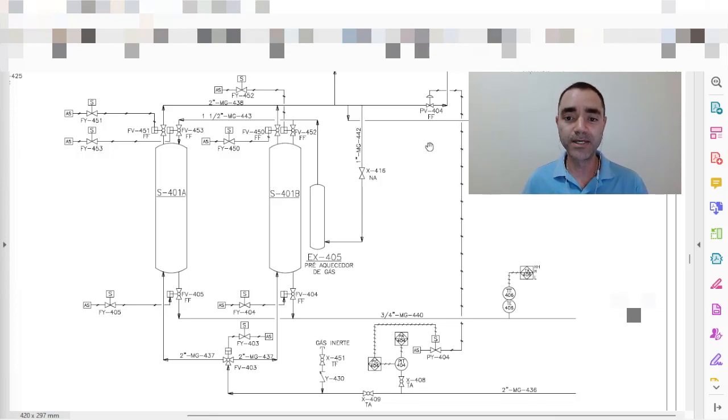I'm telling you that because this control valve is designed, or sizing-selected, to have a specific pressure drop during the design conditions. So if I am at 100% capacity, for instance, I will have here 0.5 bar as a pressure drop. This is just an example.